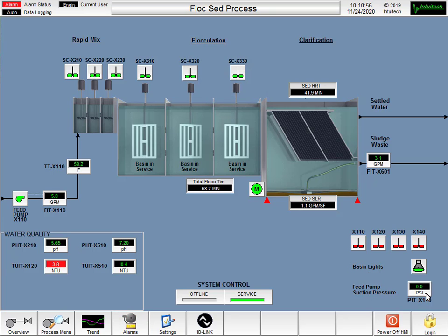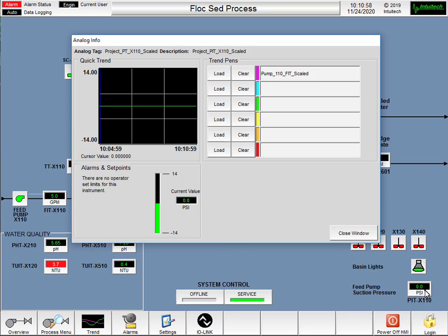The feed pump suction readout is a pressure sensor that reads the pressure on the suction side of the feed pump. It is placed in that location to allow the user to know when the strainer on the inlet of the system is getting dirty. As it gets dirty, the pressure will drop or even go negative. This has a hard-coded alarm in the system that will shut the system down if the suction pressure goes below -2 psi to ensure that the system won't damage itself.